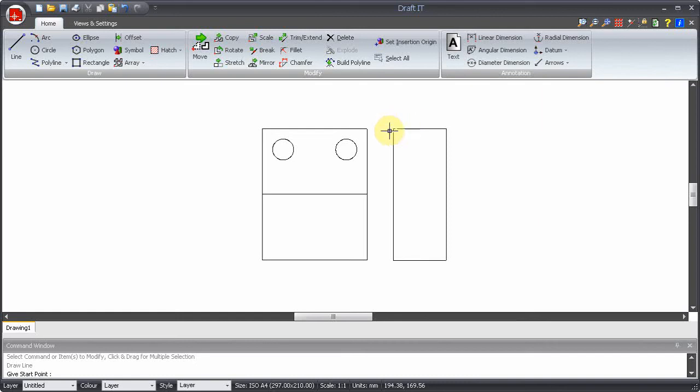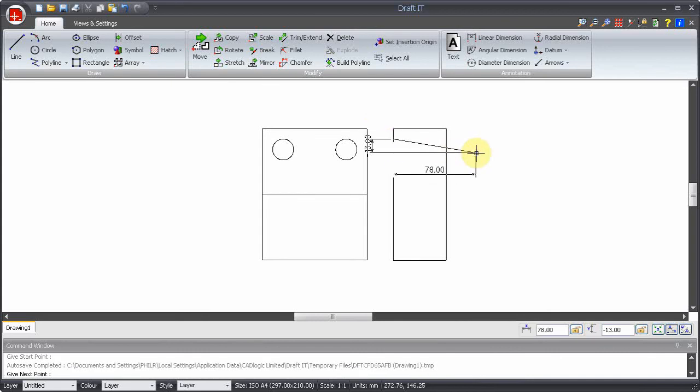Position over the point and press X, and you can see the dotted line showing the locked X value. Now we position over the quadrant point on the circle and press Y. You then see a second dotted line showing that the Y-axis is also locked. Click to accept to define the first line point. Because the XY input mode was the last one used, it is automatically recalled here. We now want to use snap mode again, so we now press F7.